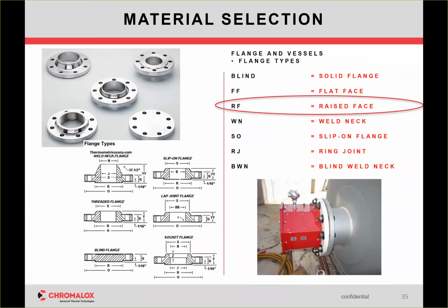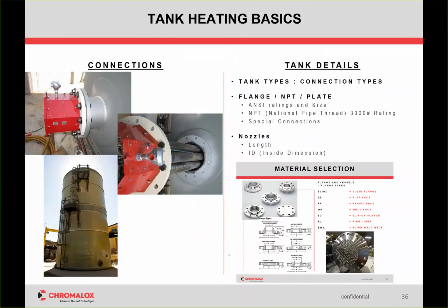When you're dealing with fiberglass tanks, you've got to be really, really cautious, because if you use our configurator, or you buy something out of our catalog, it's going to have a raised face flange. If you go mating it up to a fiberglass tank, you could cause problems. You can cause leaking. You can cause a gasket not to seat properly. Pressure over time could crack their flange. And then they look down and say, oh, it was the heater's fault, or the salesman that sold it to me, or saleswoman. In that case, you want to be really, really cautious.